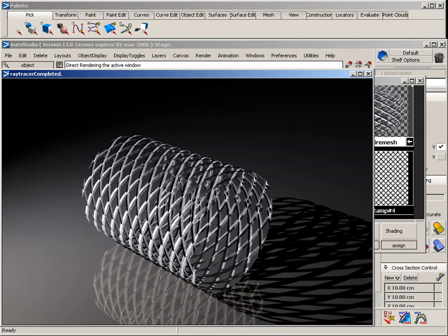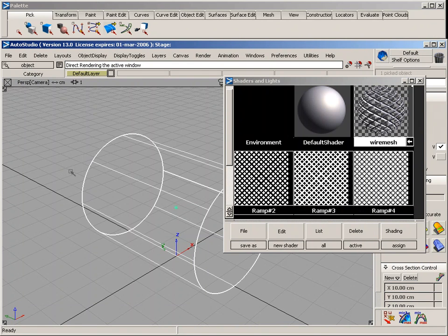Notice that changing the refractive index to 1 helped to fix the distortion that we were getting earlier. However, there's still no shadow appearing in the transparent areas. This is actually caused by the ground floor.